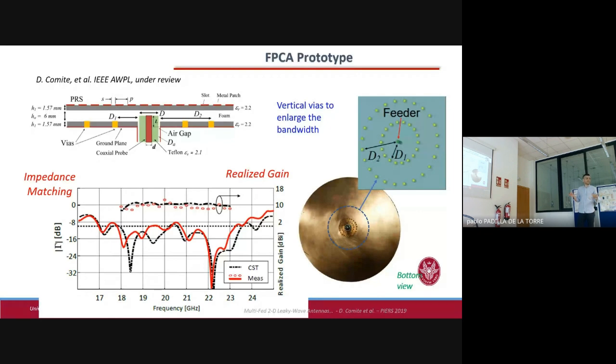You do laser etching, then you use a foam layer here, and in the end, this dielectric layer and the foam are not thick enough to be seen as distinguished by the radiation, so you will get on average a permittivity that is smaller than 2. So that is a possibility. It's a very, very simple approach.